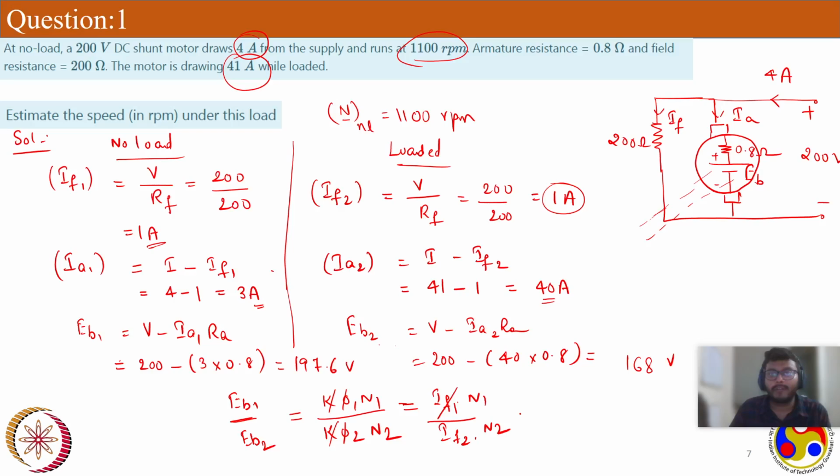I will make a line here, write what we need, and calculate it here. So now see, this is my ultimate goal: I need to achieve the shaft torque. For that I need shaft power. Do I know shaft power? I don't know. Now P shaft equals VAIA minus armature copper losses, IA square RA, minus rotational losses. That is nothing but